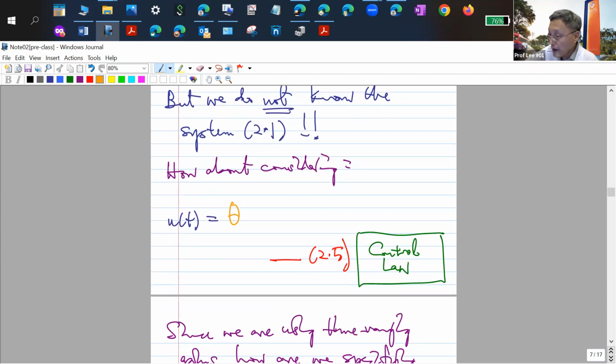All right, the state feedback. With the state feedback gains, multiply all the measurable state variables. The scaling gain multiplies my reference input. Except because I don't know the numbers, what I need to do now is make all my state feedback gains and all my scaling gains time varying.